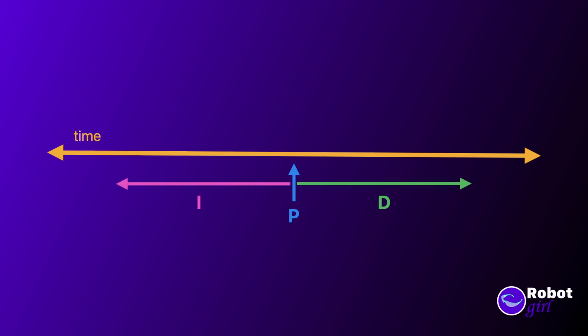To visualize how this works, let's plot two things on a graph. First, here's the set point. To make things simple, we'll keep the set point the same for the entire time. So that makes it a horizontal line. Second, we'll plot a hypothetical graph of a measured value that gets close but can't quite reach the set point. If we pick any moment in time and draw a vertical line, it will intersect both lines. The error is represented by the line segment in the middle. But in reality, the loop typically runs every few milliseconds, so let's expand that line to a rectangle that is as wide as the loop time. You can find the area of this rectangle by multiplying the height by the width.